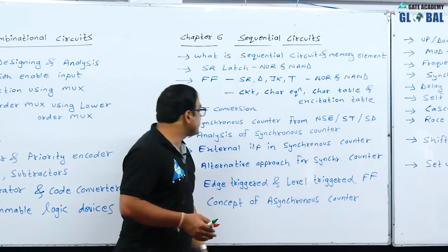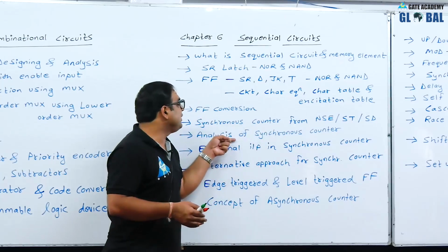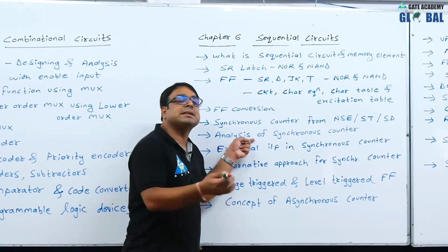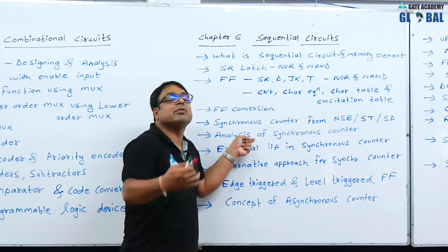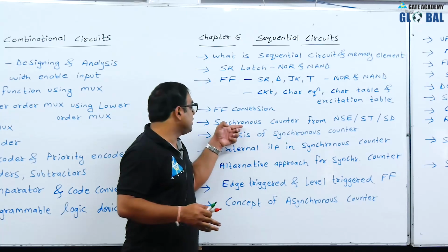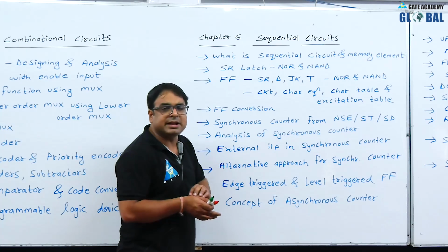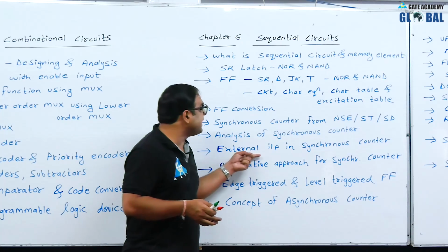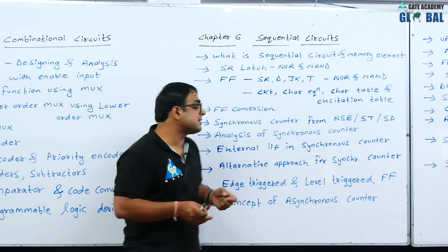Next, after learning the designing of synchronous counter, we will try to analyze the synchronous counter. Let's say if a synchronous counter design or circuit is given, what will be the state table, what will be the state diagram, what will be the sequence of states. So all the things, including designing and analysis. Now the next version of synchronous counter contains an external input, which is very important with respect to the GATE exam.